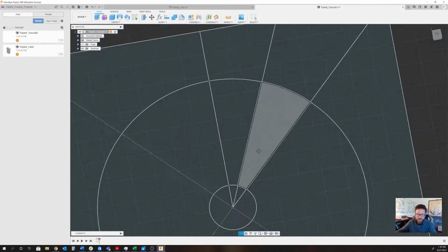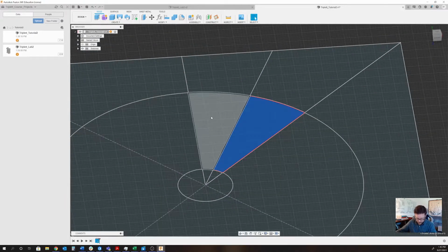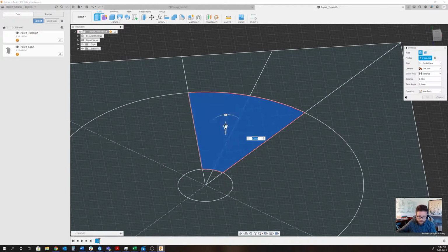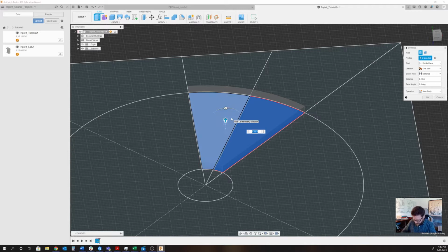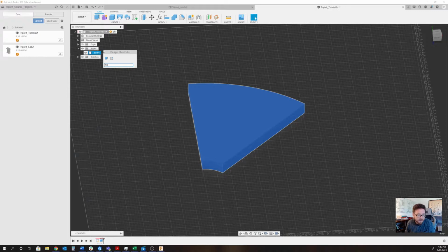And then now I can hit shift and change my view a bit. And I can see there's all those points, all the lines. I'm going to hold down shift and pick up both of these two wedges. And I'm going to extrude them up 0.2 meters, which is maybe 8 inches high, around there. One thing that you may notice when you first create your first body through an extrude tool is that I'm going to call this one stair.